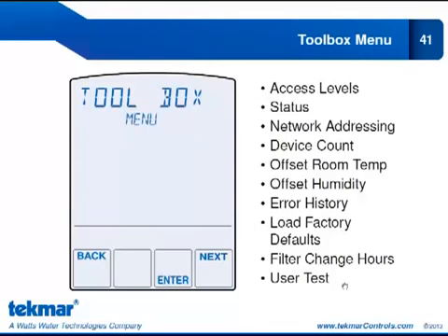So we can select the heat or cool sequence. It will go through a series of tests, and there is a chart on page 6 of the installation and operation brochure that will show you which relays close in which order.